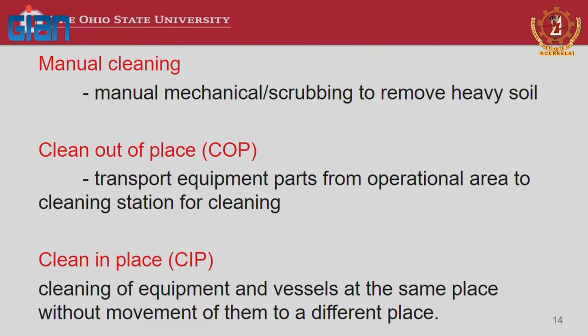So, manual cleaning, obviously you scrub and remove the heavy soil. The second is COP, where you transport the parts from the operation area to a cleaning area and do it there. CIP is basically you do it in the same location. So, that is the 3 different places.